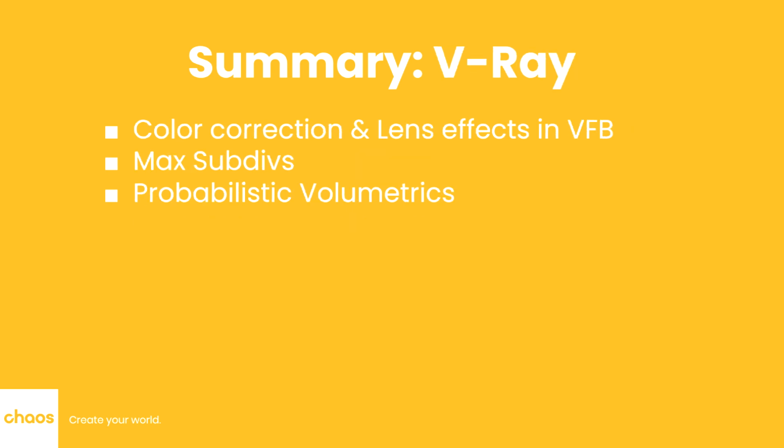To improve rendering speed, we tweak the max subdivs and probabilistic volumetrics. We also added a final touch by applying color correction and enabling lens effects in the VFB.